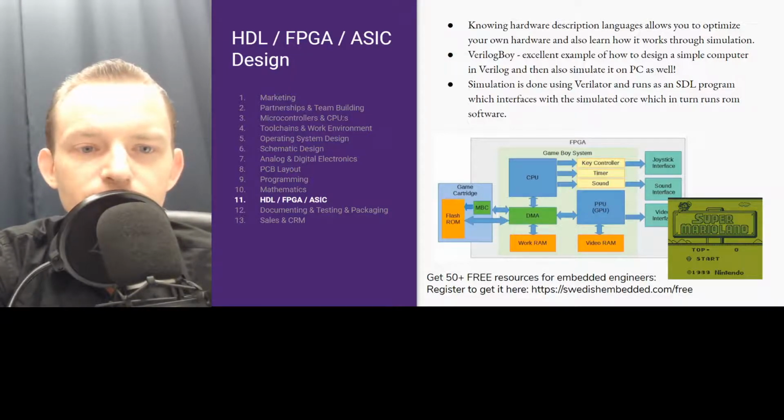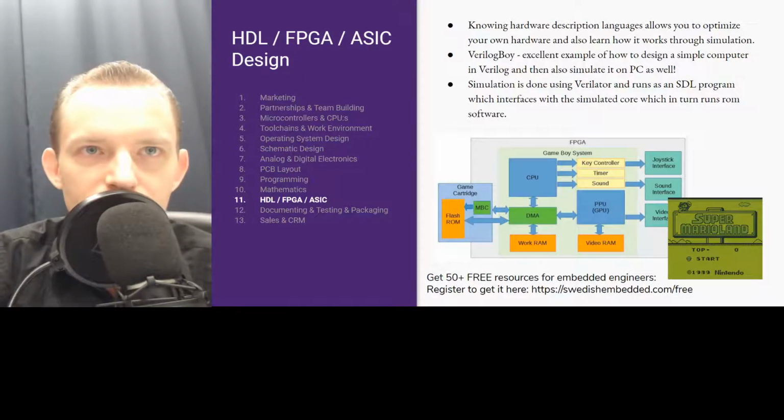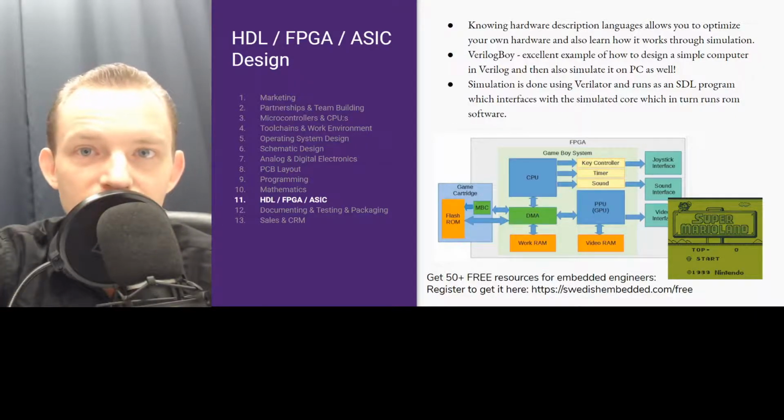Because it's implemented in Verilog and compiles under Icarus Verilog, which also has a tool called Verilator that compiles the Verilog into a simulation. And you can then actually run the simulation, and you can feed it with binary code that then runs on the simulation, and the simulation then produces an image of the screen of the Game Boy.